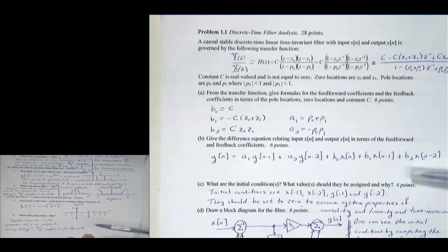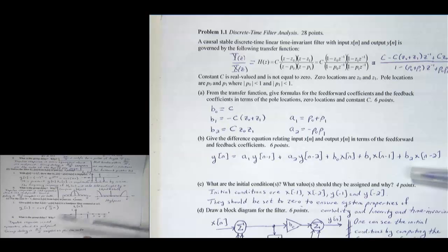Part C, I try to make this a little more tractable by asking you to do the three coefficient case, so you could get your hands on all the values more easily. So here I say now let's try to get the bandpass filter, h1[n], from the low-pass prototype by multiplying the low-pass impulse response by some sinusoid. And I ask that we want to send the passband to pi over 2. Now there were some creative answers to this one, and they were pretty good. I had to go back and think about it.